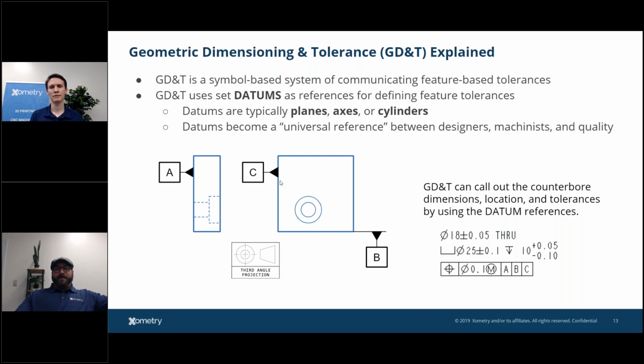If you don't give us a datum, we could be measuring off the wrong edge, we could be manufacturing off the wrong edge, and you could get the wrong tolerance stack. Yeah, and even when you plane the blank, so even when you're running a face on your blank material, you're facing these datums because that's going to be the most critical reference area as you fixture your part. So calling these out is extremely important, as well as how you put your dimensions.